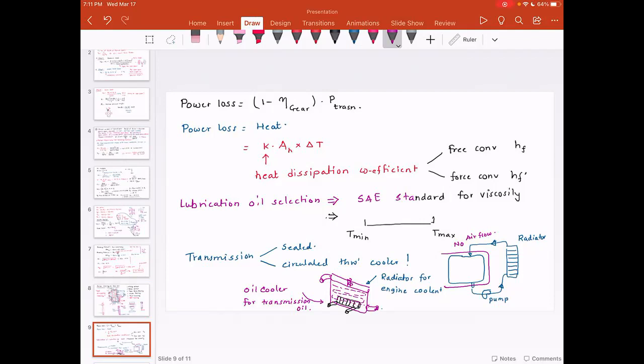But over a period of time, say 3,000 miles, 4,000 miles, the amount of debris increases. The filter loses its filtering capacity, and oil doesn't get purified or filtered to the extent that we really want to. The oil starts degrading. Oil cannot carry out the sufficient amount of heat, and you will notice that oil starts smelling burnt.